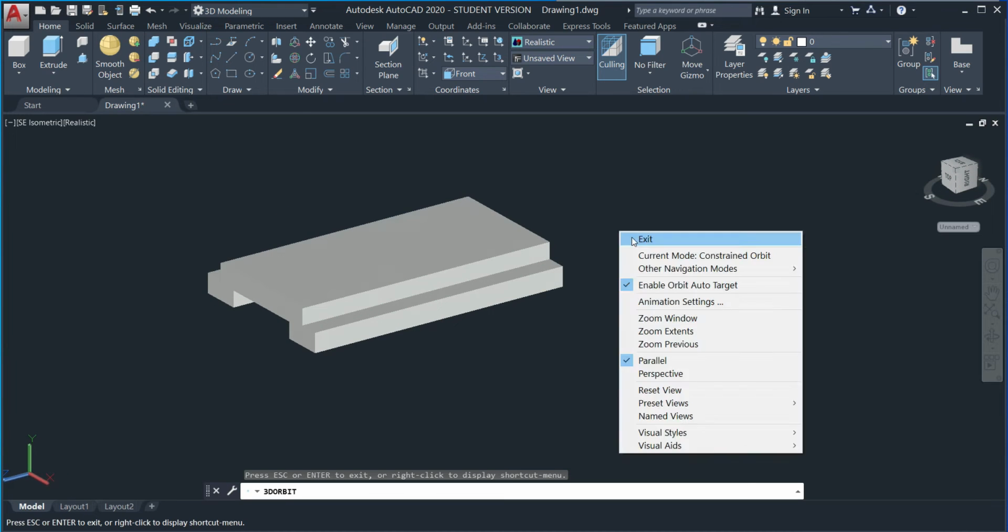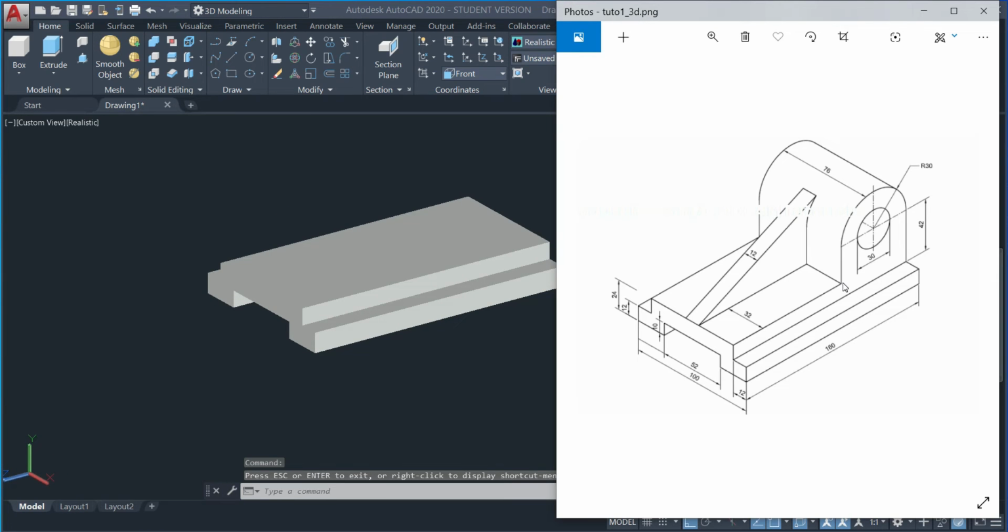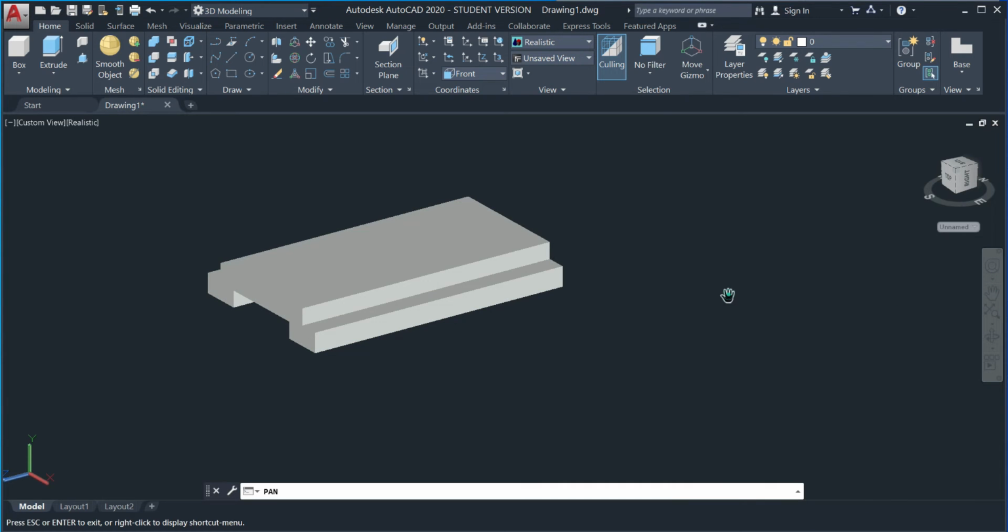Okay, now we will construct the other faces. So let us first construct this particular part of the object. Okay, so as you can see here, we are firstly constructing a rectangle of length 60, because this circle has a radius of 30, therefore the total distance from this point to this particular point is 60, and this height here is how much? Total is 42, and this particular height is again 12, we know it from here, therefore 42 minus 12, you are getting 30 as the distance. Okay, so 60 and 30 are the dimensions of the rectangle. So I will construct it separately.